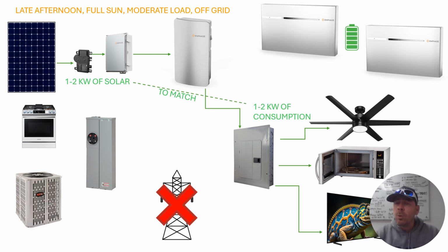Okay, now we get into some interesting things, and this is what really confuses people too. They see, wait a second, my batteries aren't doing anything, or my solar is not producing as much power as it should. Well, that's because the smart components of the computers that are built into the system start regulating and modulating the system. So if your batteries are in a full charge state, then there's no purpose in discharging them when the solar is still active, as long as the solar makes up the capacity that you need for your loads and your consumption for your backups.